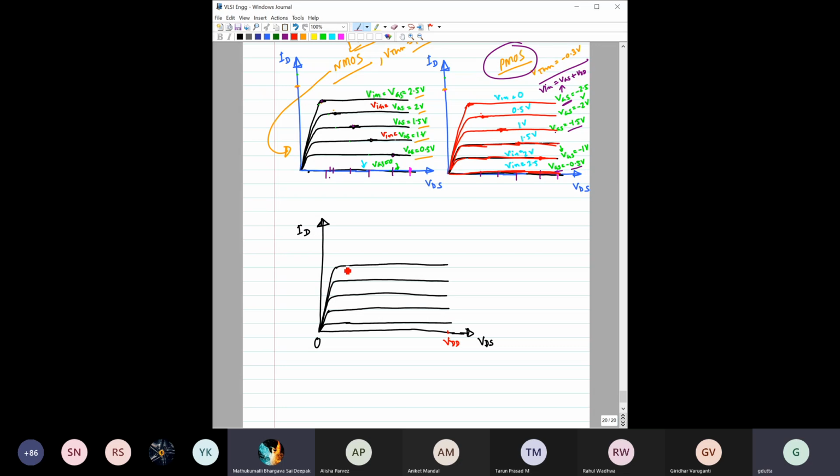So how then would the curve look like? It is not so easy to draw it and properly get the VTC, right? So let us do it step by step. Otherwise, we will miss a couple of points. Let us first take this VGS of 0.5. So VGS is equal to V in, so basically V in equal to 0.5.